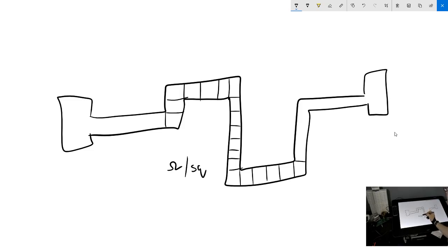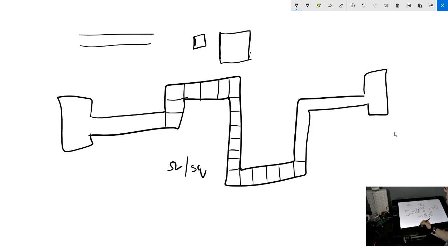And the interesting thing is that squares are kind of unitless, kind of dimensionless, because if you have a square that looks like this, it has the same resistance as a square that looks like this, as long as your contact area is across the entire thing. The reason is that if you lengthen a square, then you're increasing the resistance, but if you widen a square, then you're decreasing the resistance.